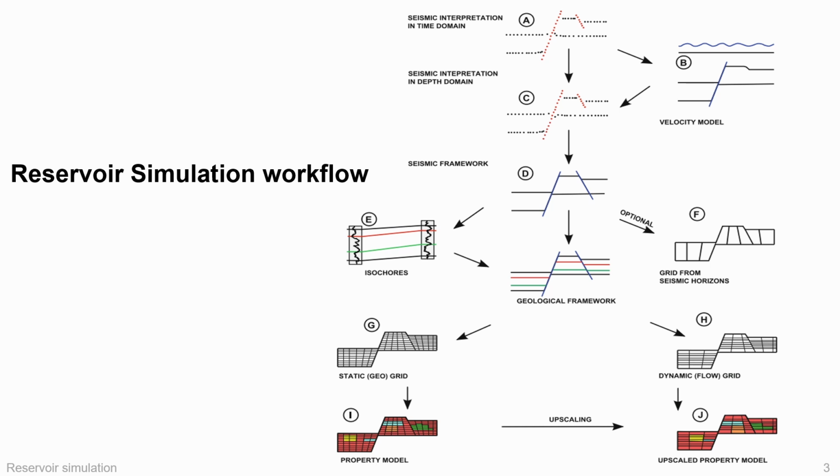First, gather and input rock and fluid data. Second, choose numerical grid features such as number of cells and cell sizes. Third, set the well controls, such as injection rates and bottom hole pressure constraints. These controls drive the dynamic behavior of the model. Finally, choose the outputs you want to save and analyze, such as average field pressure, cumulative oil, water and gas production, individual well pressures, and spatial saturation maps.